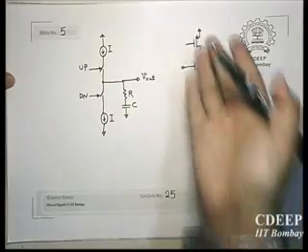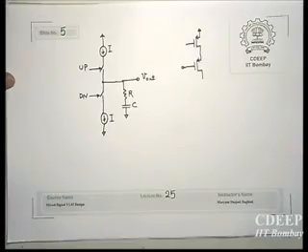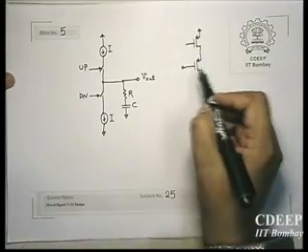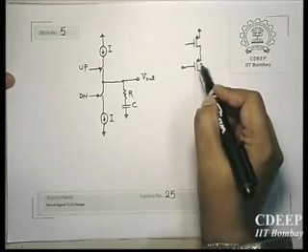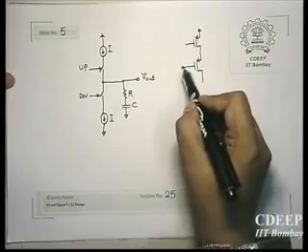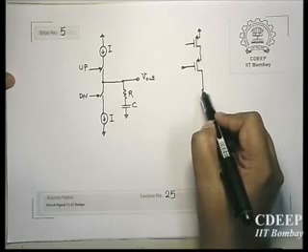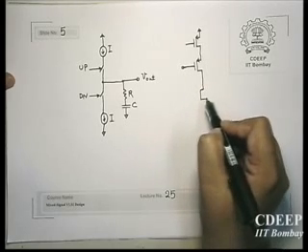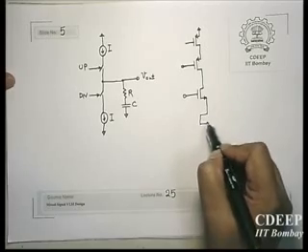Naturally, because you have a PMOS current source, you need a switch which should operate. This can be just one PMOS switch, or it can be a transmission analog switch in the form of a transmission gate, a combination of both. And then one NMOS.